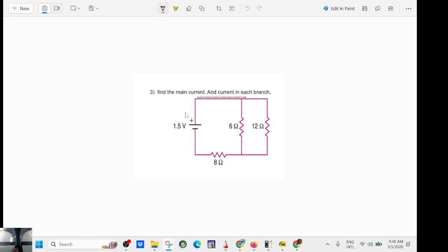And if you want to use the engineering way to solve the circuit, you start with the power supply. This is what's called a complex circuit, but it's not that complex. A complex circuit is really when you have more power supplies. So in that case, it's easy. You go along, and nothing happens. Ooh, I have two lanes. So you make two lanes here, 6 ohm, and then you have 12 ohms. Combine again, and you have 8 ohm.